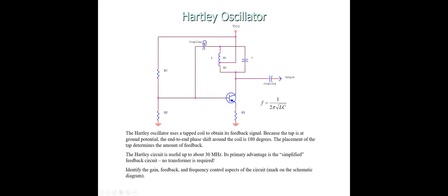So here you see this coupling capacitor, and it is there to block DC currents between the base and the collector circuit of the amplifier. You might wonder how a technician can tell that this is the coupling capacitor merely by looking at it.